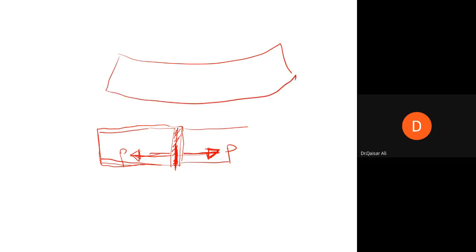You can see the lower fibers of the beam are being stressed in tension. This stress in tension will create a crack. There will be many stress components like this, so a crack will appear perpendicular to the direction of these tensile stresses.